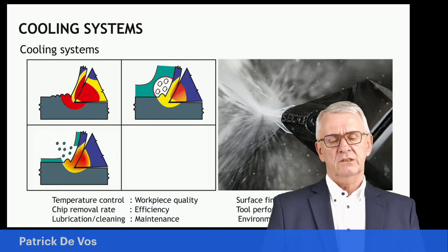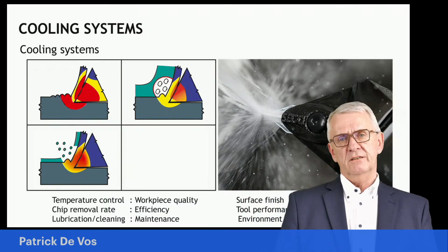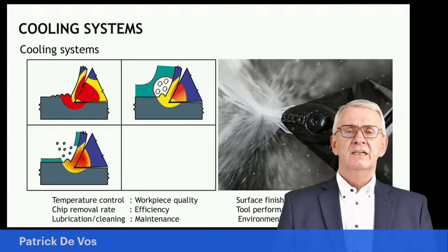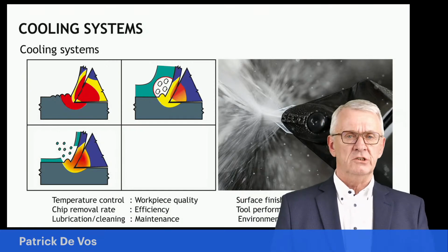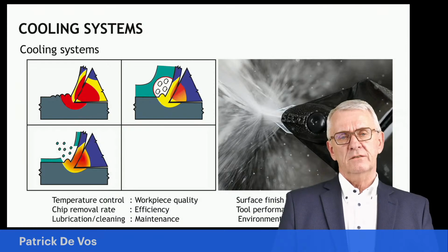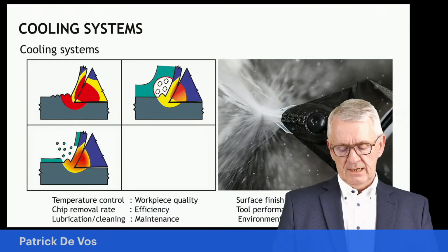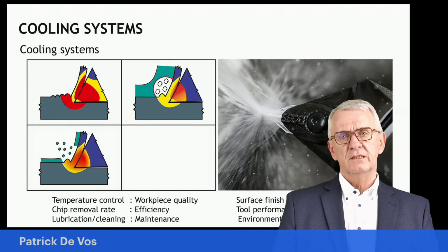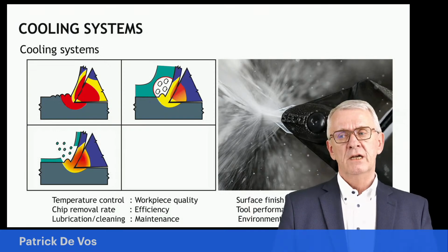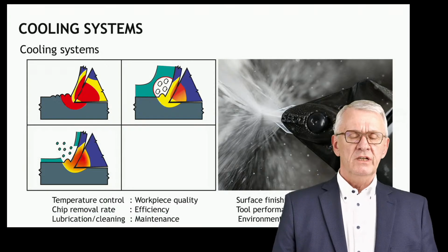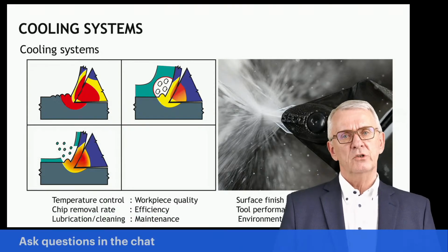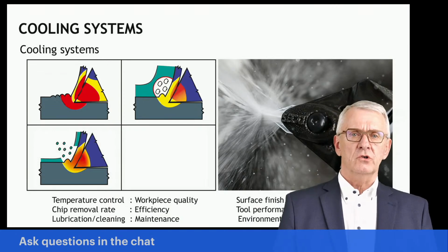A further development on this is the so-called MQL cooling. MQL is a different physical approach to the same thing. How can the heat which is in the chip be evacuated out of the chip, so more heat can go into the chip, so more heat leaves the cutting zone? With MQL, we count on a different physical principle. It's like when you jump in a swimming pool in summertime, you cool down because the water is cold. That's what we do with emulsion cooling. When you come out of a swimming pool, you have a thin layer of water on your skin, and that evaporates in the sun, and that evaporation process takes heat away from your skin. So this MQL system also works.